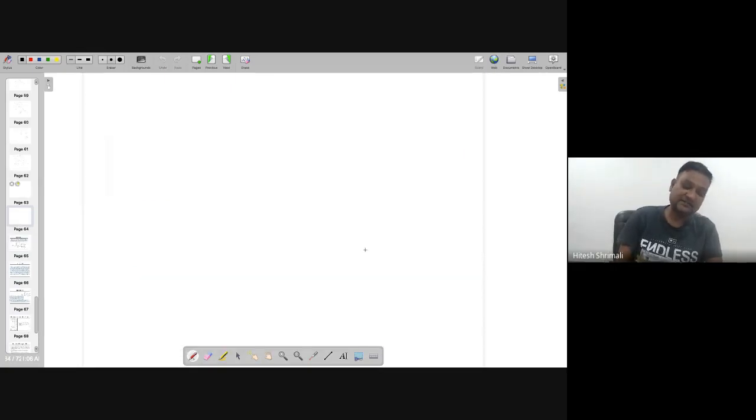In such cases, we replace the small letter notations with capital ones, where F is nothing but GBH plus P. But we also learned that the path effort is not only GBH, it is going to be raised to 1 by N, times N. So that's the final equation for finding the path delay.